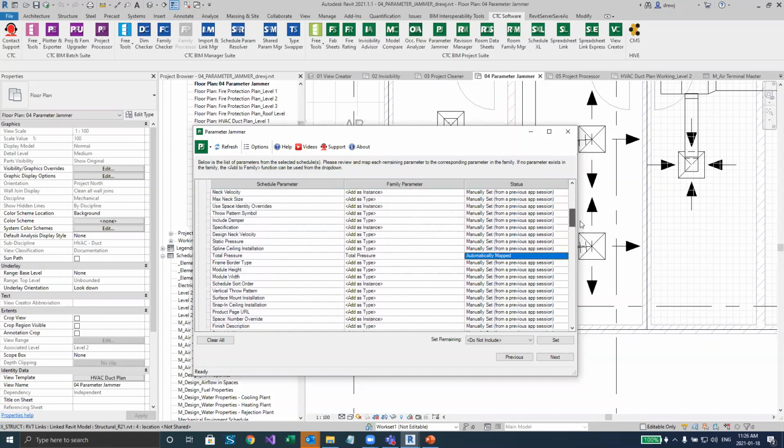What that will also do is if we have a value inside of this parameter, it's going to take that information and move it into the shared parameter that's being added in there, which is a really very useful thing. We could have useful data inside of our family already, and we want it to show up in a different column inside of the schedule. Well, it enables you to do that via mapping. So that is all for the one family type at the top there.